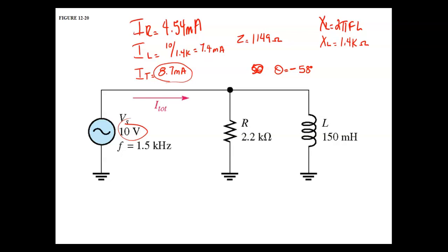So US Steel ran a big old synchronous motor out there. And you can actually overexcite a synchronous motor and it creates a leading power factor. And you can electronically control that. So you literally can make a dynamic power. Some of the switching stations have a switch gear that actually switches different size capacitors in. You can actually hear them clicking out there to help do what? Help manage the power factor. Synchronous motors are the most popular one.